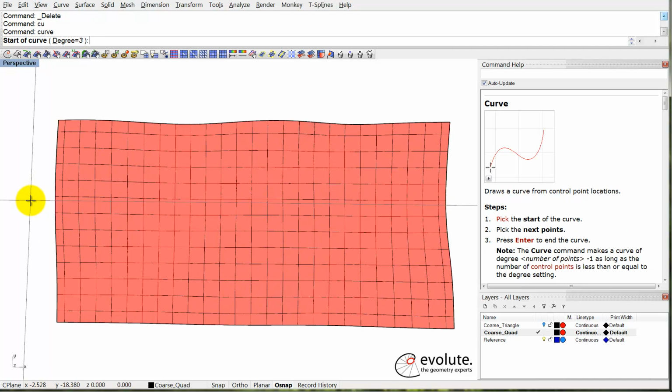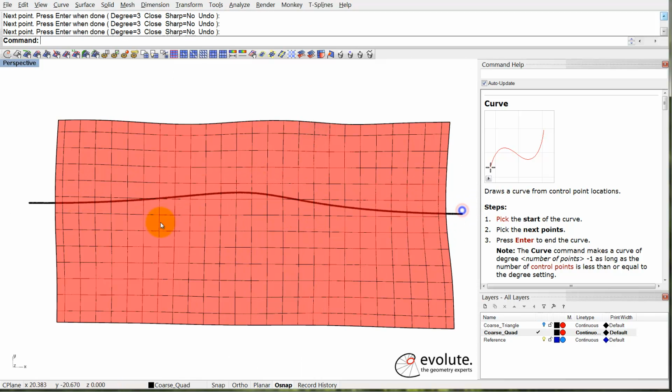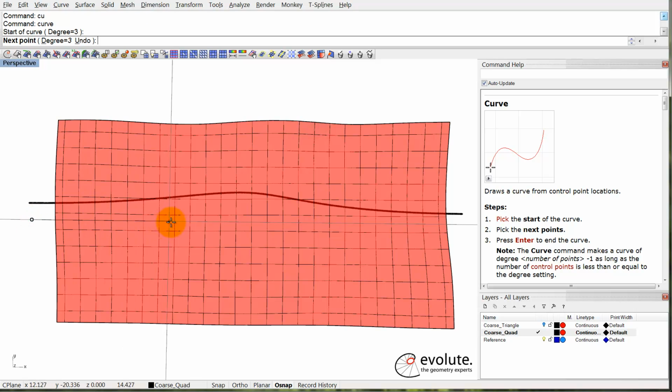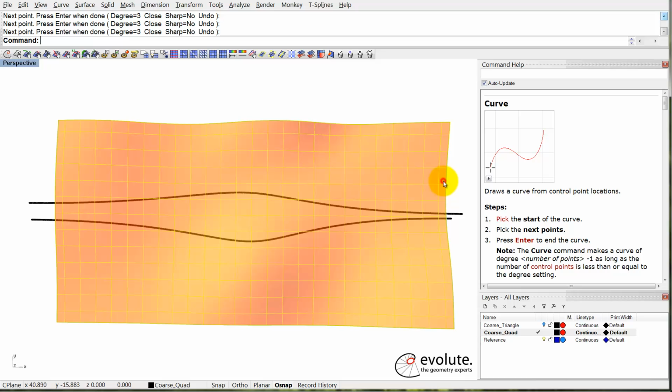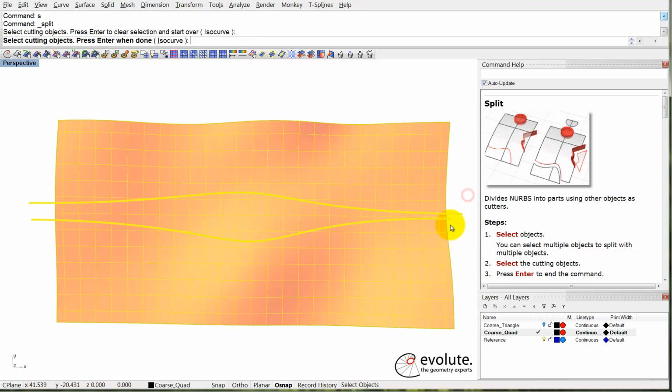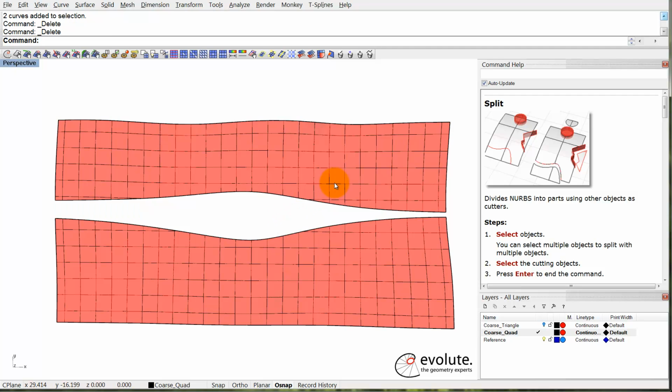It's smooth, but I'll start to chop it off to get some sharp features. Alright, so I'll draw up some curves over this thing, something like this. And I'll split the surface with these two curves. Just delete everything which I don't need.